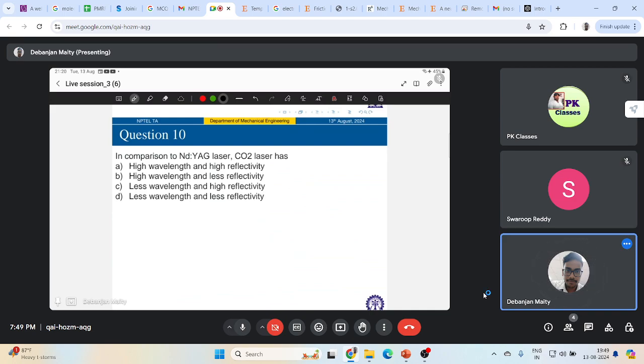So laser beam welding is a process where, of course, you'll be using a laser beam. This can be either a solid state laser or a gas laser. In either case, the laser beam will be focused and directed by some optical means to achieve high power density. In a solid state laser, a single crystal will be doped with a small concentration of some transition element.